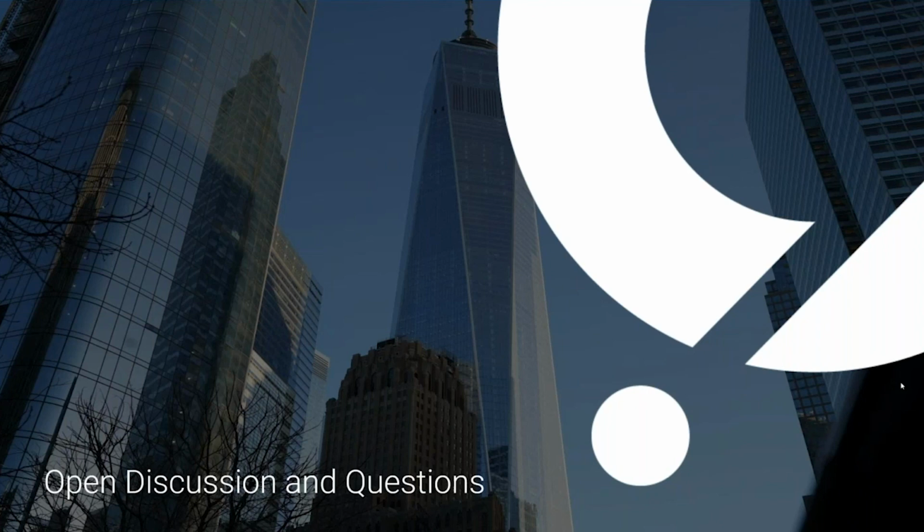Great, thank you for that. I have another question here, maybe this is for Brent. Brent, how far back can the virtual detectors be placed from an intersection? Yep. So optimally, it is a little bit of a factor of camera height, but assuming you're, call it, 25 feet up, we're looking at about 150 feet to the stop bar. And then from the stop bar back, you can go 40, 50 feet. So we're looking for the stop bar range to be within about 150 feet. The higher the camera goes, the more that expands. So if you can get the camera to 30 feet, it gives you an effective range that's a little bit further back, and so on.